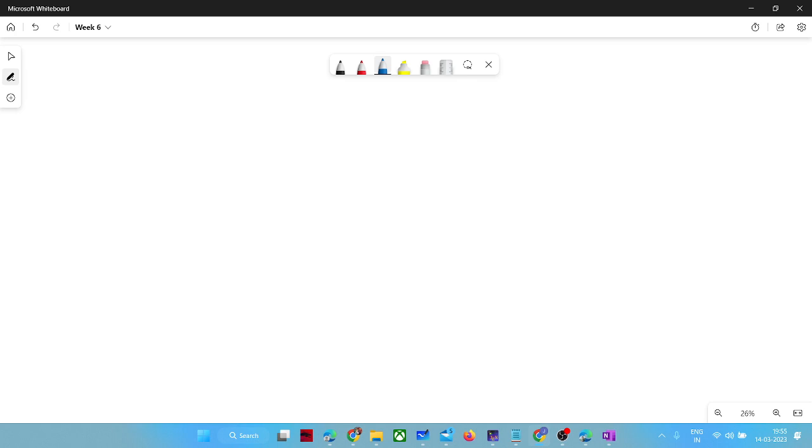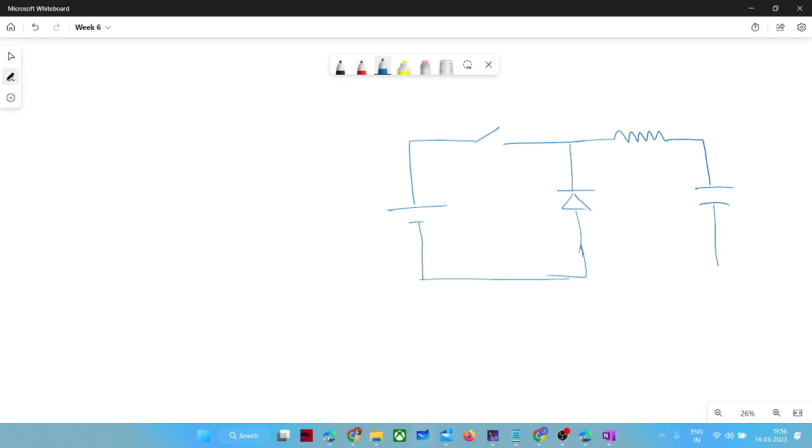Anyway, he is not here, but I will discuss it. He asked why this voltage is not being created. Just let me draw this circuit for the buck converter. So this is your VL. When this switch was on and this diode was off, your inductor was charging and the inductor is acting as a passive device. So VL polarity would be like this, right?